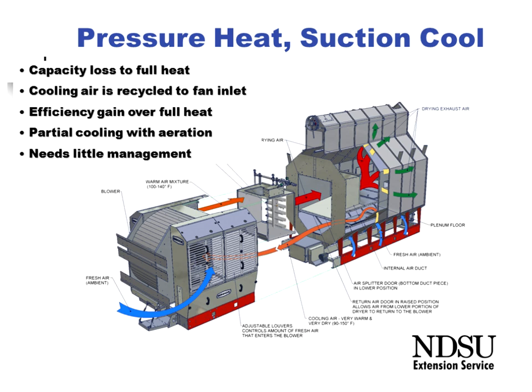Now, when we compare the energy efficiency of doing the cooling in the dryer versus doing it in the bin, they're going to end up being fairly close. Here we're capturing the heat, but we're doing it immediately as part of the dryer, so we don't see probably as much moisture reduction as what we might with what we call dry aeration, and we'll cover that a little bit later.